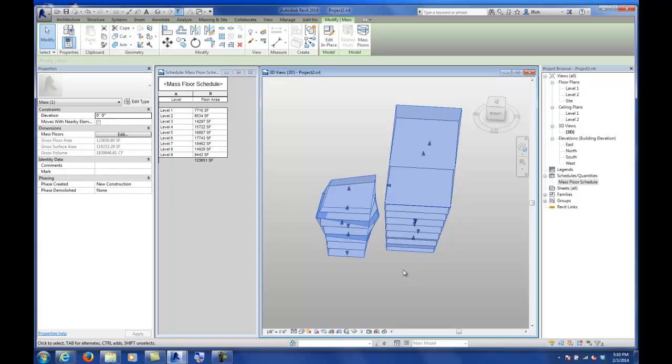Yeah, I guess you can basically cut it out with voids. I'm not sure what you're peeling, how it's peeling back. But if you start to move an edge, it's basically going to pull everything with it. So the mass is always going to be this solid geometry. But if you wanted something more cut out of the corner or something like that, you'd have to do this void mask that would start to cut it out. So it might be a little limiting at times, but those are the tools that you can work with.